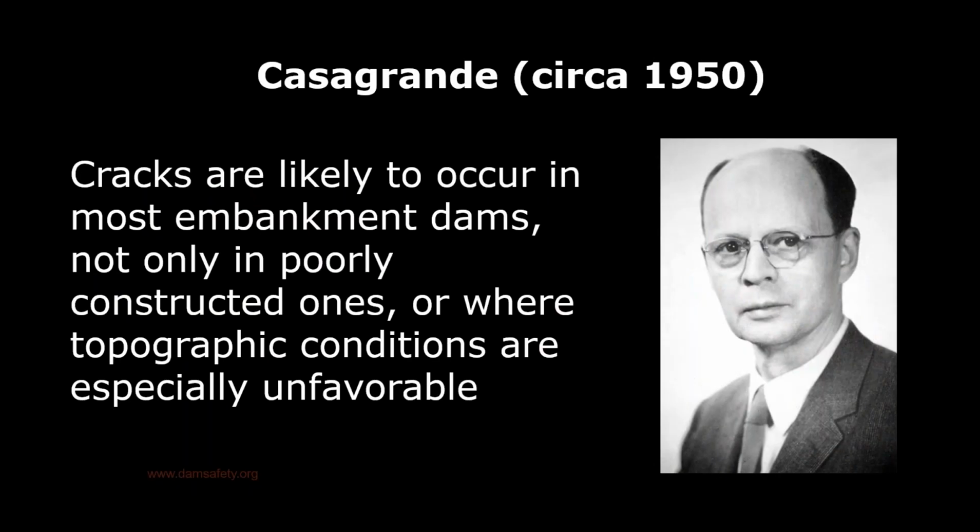As you're inspecting an embankment dam, something else to be aware of, and this is something that an engineer whose name is Arthur Casagrande, his contribution to this field was, if I was to summarize what he would say, is pretty much assume that if you're inspecting an embankment dam, that there's a crack in the dam, because all the embankment materials pretty much are susceptible, if they're well compacted, to cracking.